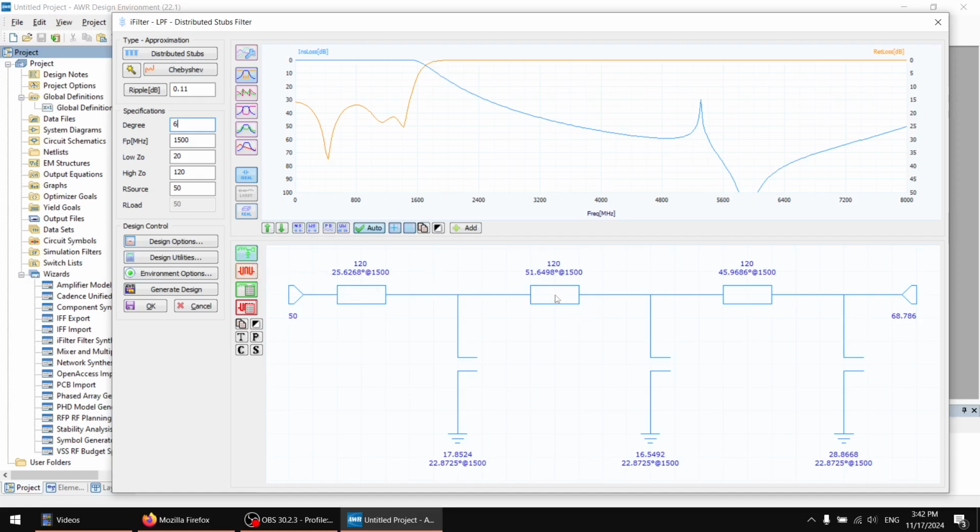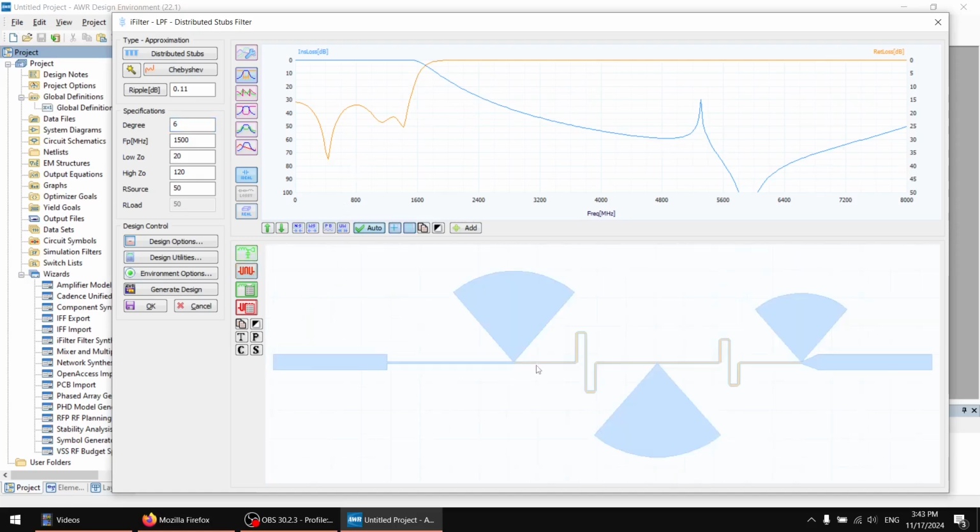This is our pi structure of this filter of the sixth order of a Chebyshev, and you can see that it's calculating it correctly. This looks like a low pass filter indeed, but this is your physical structure, and you can see that there's a problem with those inductors here because these thin traces have a higher impedance than these white traces, so they act as coils especially, not because they are coiled, but because of a higher impedance that they present for these frequencies.